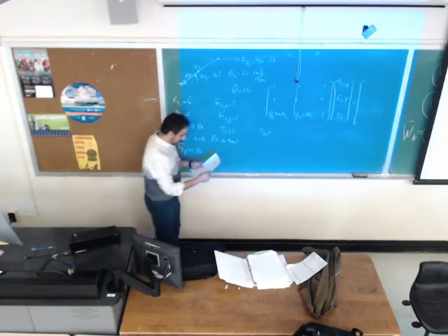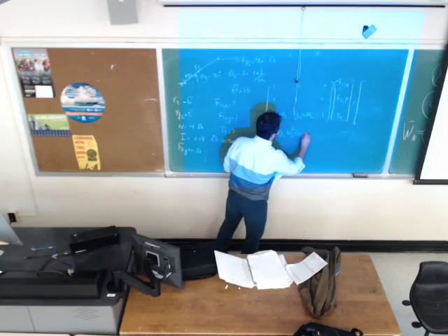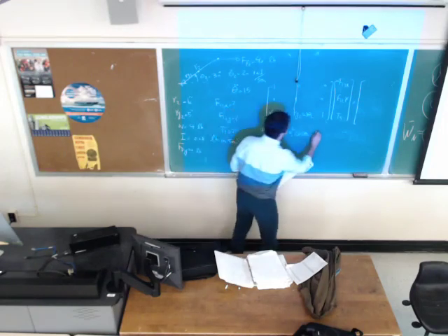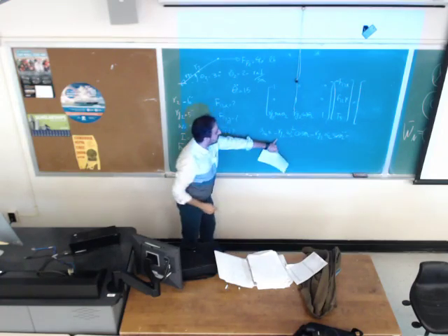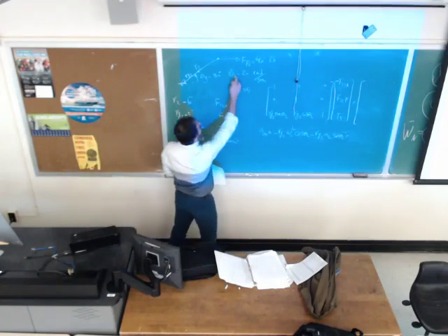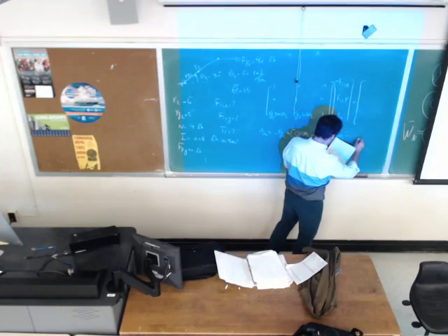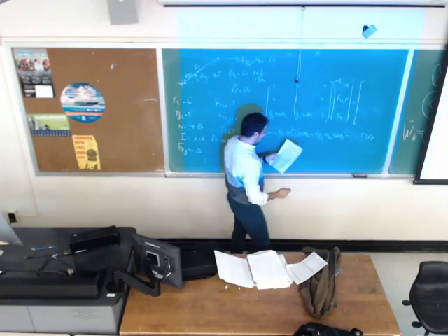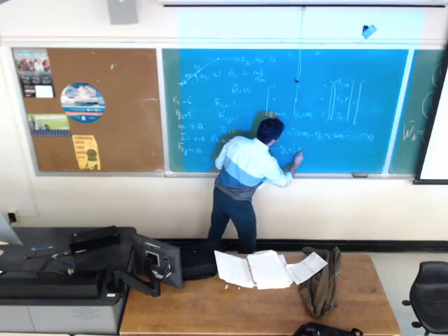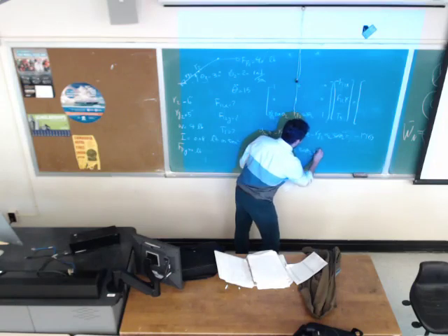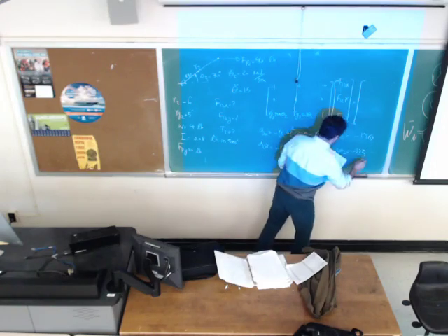The acceleration of center of gravity in x direction is going to be negative RG2 omega 2 squared cosine of theta 2, which I derived in yesterday's class, minus RG2 alpha 2 sine of theta 2. RG2 is 5, omega 2 is 20, and theta 2 is 30 degrees. So you have these terms, and you will end up with negative 1769. And ADY is negative 9, negative 5.